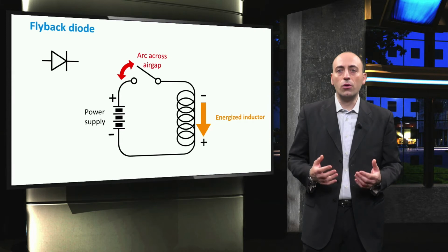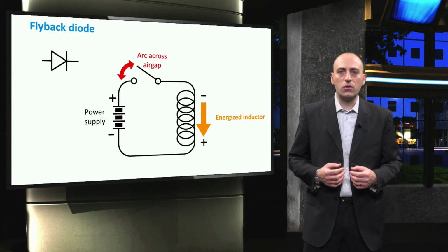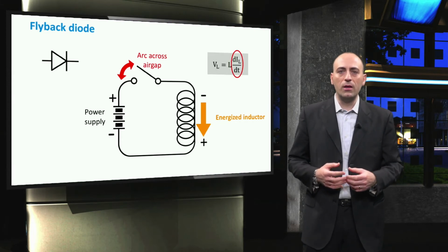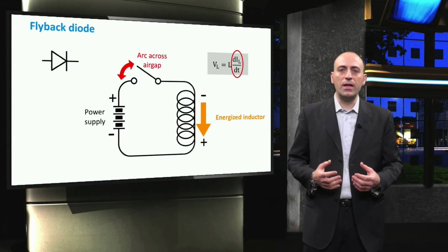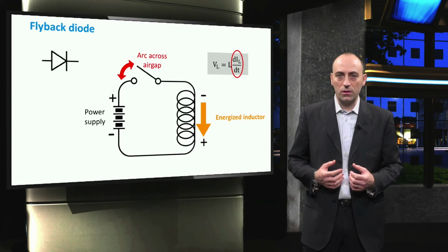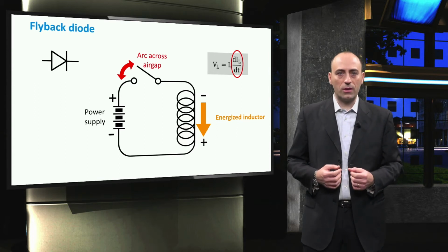Problems might occur when the switch is very fast, so you have, in a very tiny amount of time, that the derivative of current becomes very high. This can be potentially dangerous since, if the necessary environmental conditions are met, you could even have a spark.